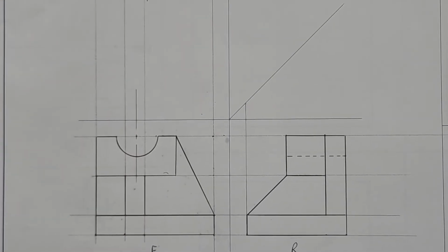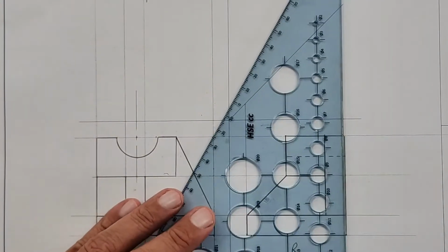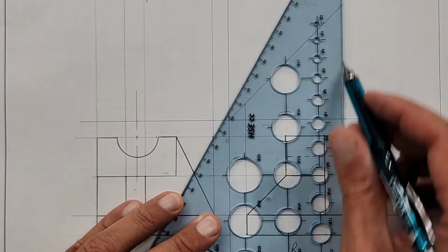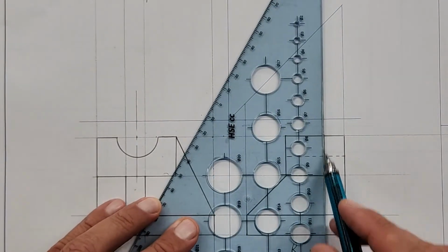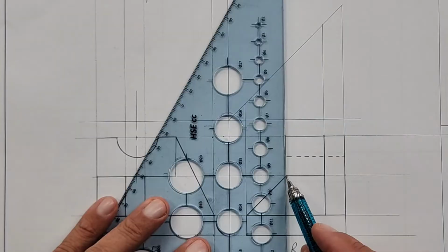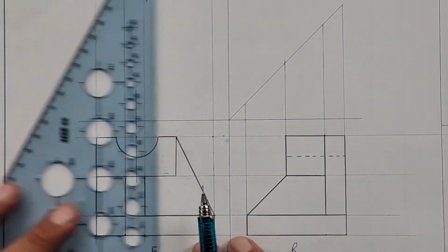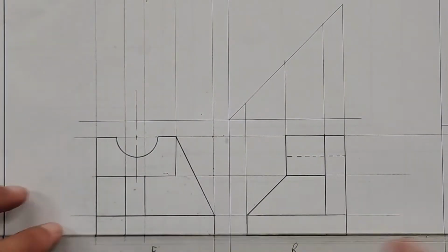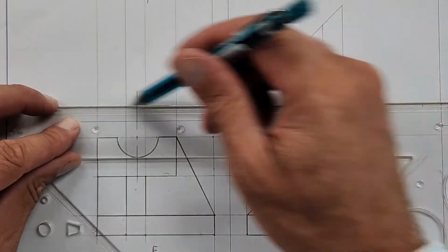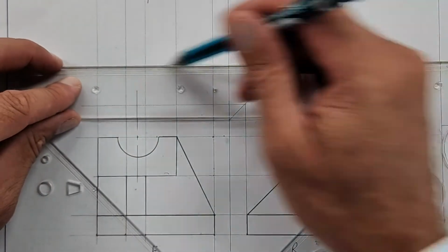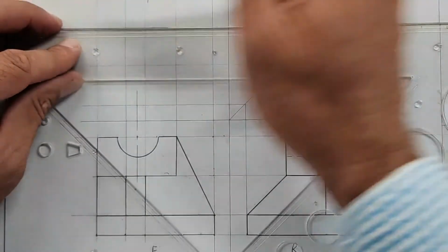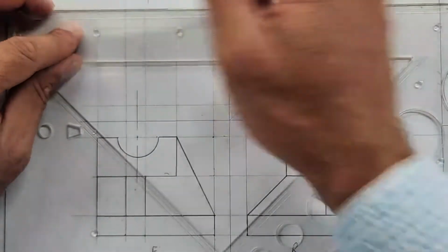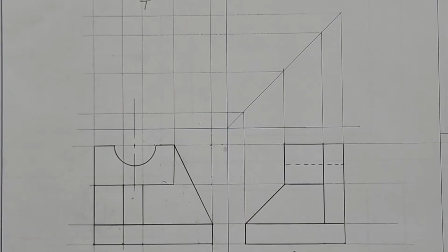Now we start projecting what is given to us. So we go up here to the 45. Same on this one. Same on that one. You can project these up. All right, and now across at that 45. And so we're just creating a grid similar to what we had yesterday when we did these drawings freehand. With our new grid now, it's going to be quite quick to fill that in.